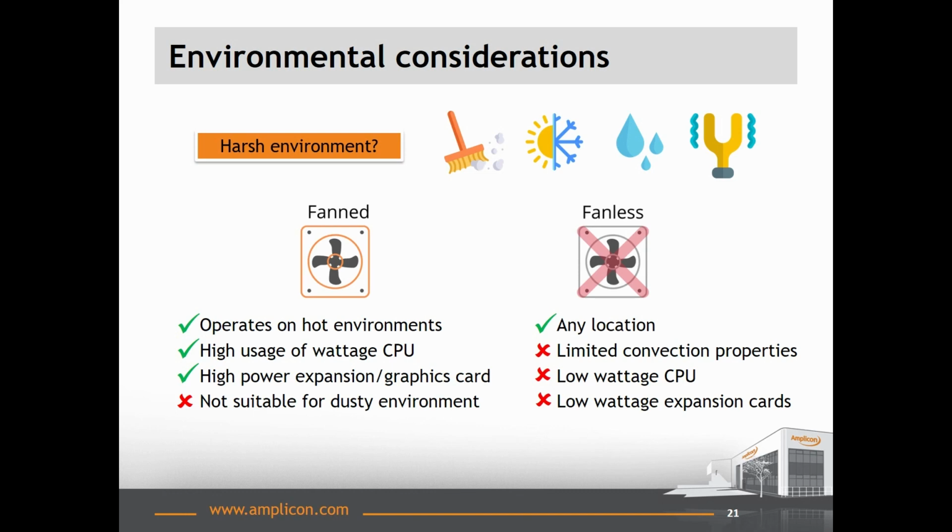On the other hand, a fanless solution allows you to install the PC pretty much anywhere, but now you are limited by the convection properties of the heatsink, which will force you to go down to a low wattage CPU and a low wattage expansion card.